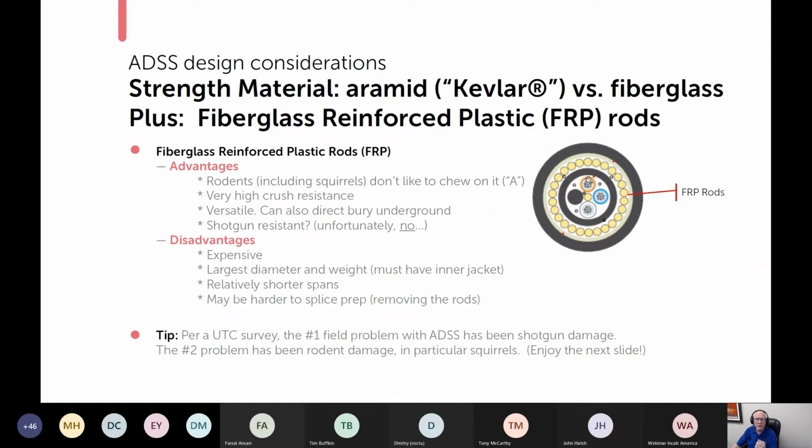So you would use PBT as a tube, completely empty. I say completely empty. You would go ahead and either, if it's a dry tube, put a yarn in it, or use the gel in it. But I mean empty with no fibers, and that's a reasonable compromise because then you're reducing cost. You don't end up with this real strong element that's adding weight and cost, but really giving you no effective benefit.